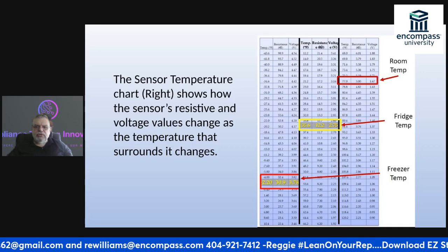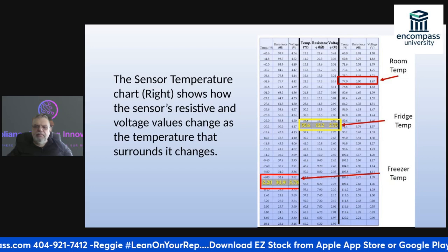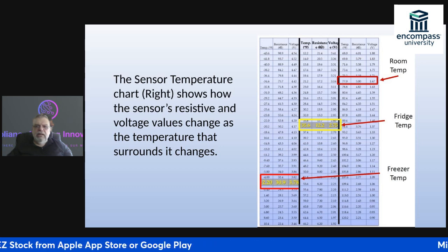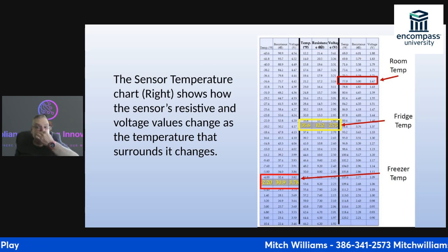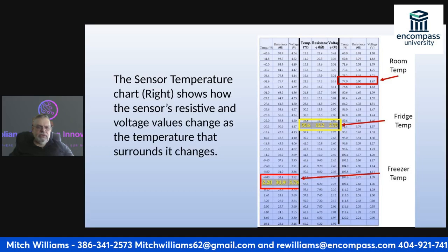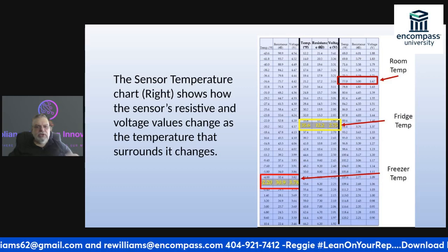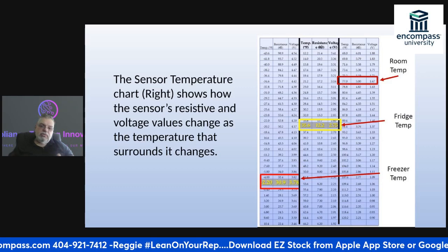Okay, as opposed to if I come over to, if the temperature is 77 degrees, say I have a bad sensor, I'm going to look at it. It's going to be 77 degrees outside. My resistance should be 5, and I should have 1.6 volts. Okay. So this is very important to remember, because this is not what you would think.